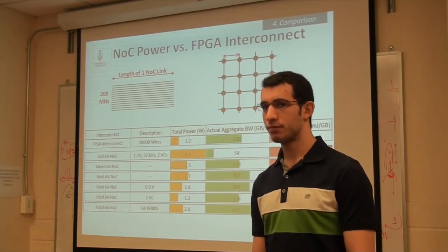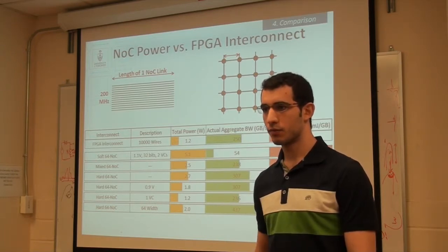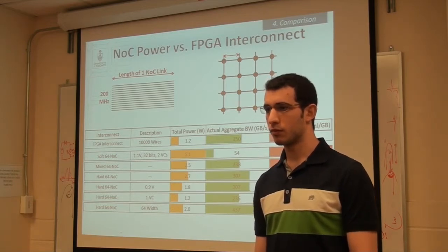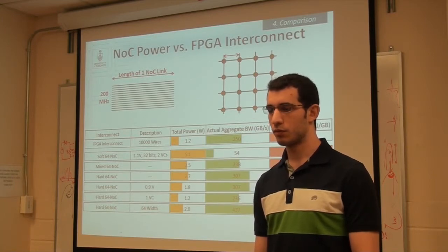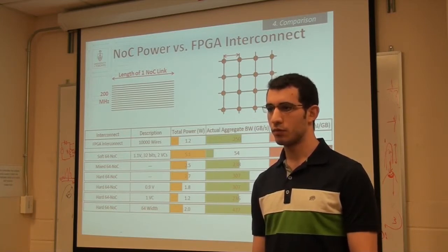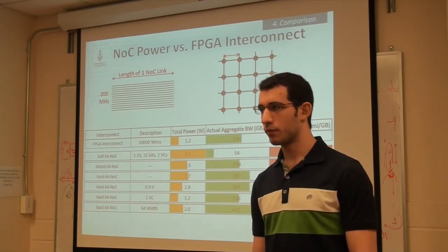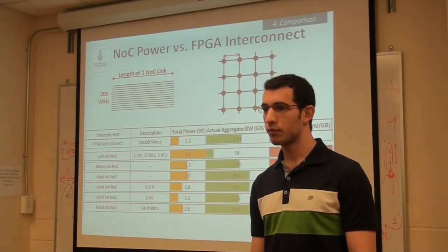There are other interesting things that happen, like if you're not running at a frequency multiple of the DDR interface. So as Mohamed showed, when you put in those 512-bit wide asynchronous FIFOs, they chew up a lot of power and area very quickly. They also add latency. So that latency comparison I just mentioned to you was at a multiple of DDR, which is more favorable to QSys. Because in the hardened NOC, the fabric port does the asynchronous FIFO at a high clock frequency. And narrower too as a result, so it takes up less area. Yeah, it's narrower, hardened, takes less area and power, because it is done before the width adaptation.